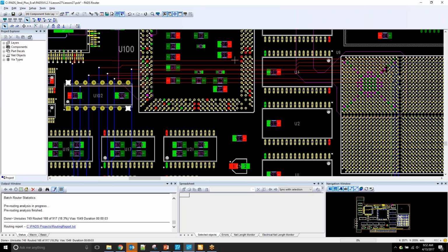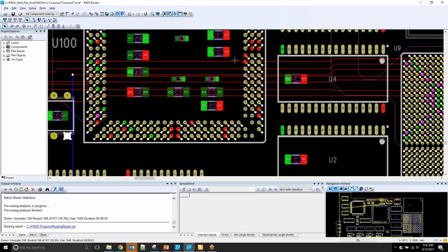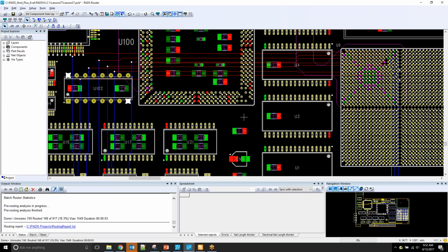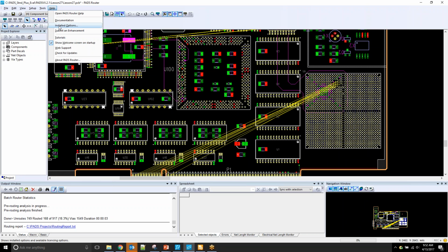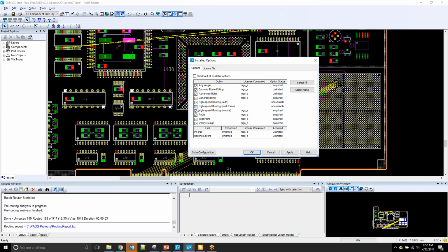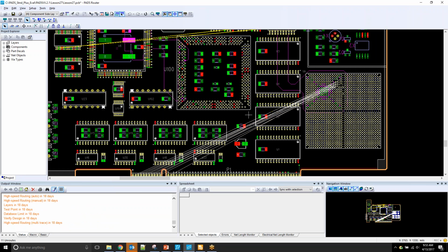Within here, we're going to have to go in and actually do some manual insertion of accordions. As you can see, this just might be a lot more. This goes from being a very quick operation, just right-clicking, routing, and having the tool tune it for us, to having to actually go in and insert accordions by hand on a one-by-one basis to make sure everything is matched up. Okay, so I'm going to Control-Z one more time, and I'm going to turn those options back on. So what I can do again, I'm just going to right-click and route, and it will insert those accordions.